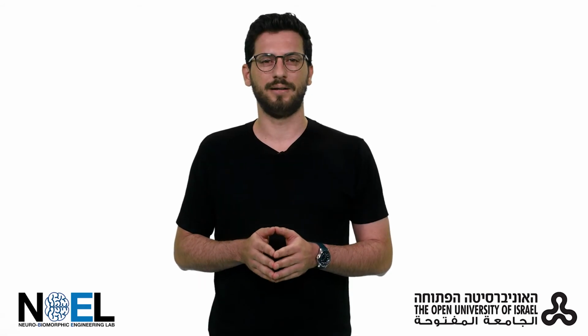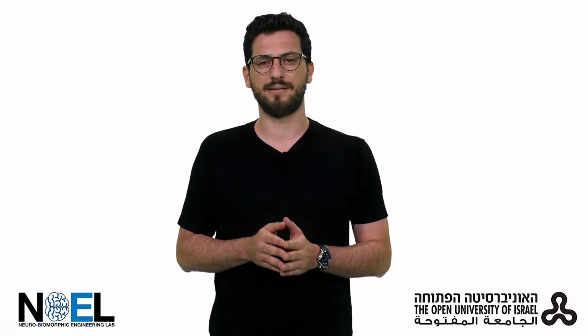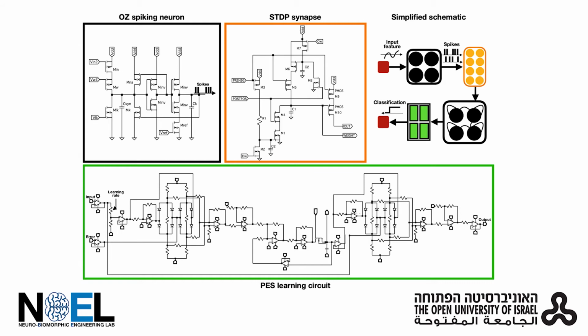To implement learning in real time, we designed an analog circuitry realizing the PES learning rule. The weight is implemented as a transistor-capacitor memory cell and is continuously modeled using a recurrently connected summing amplifier. The error block can be turned on and off, allowing switching between training and inference working modes.